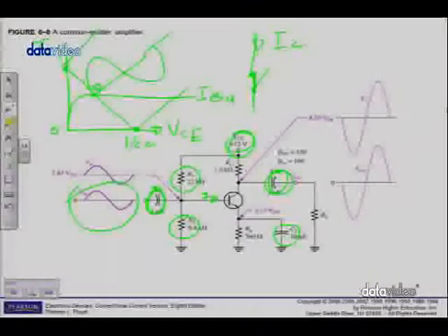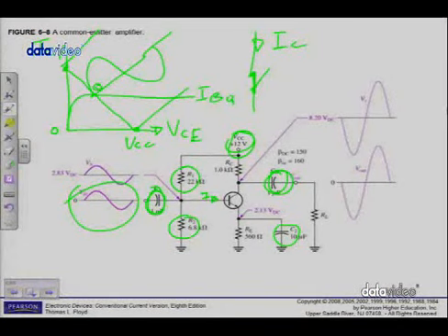This capacitor here and this capacitor here are called coupling capacitors. They couple my amplifier input signal and output signal. My input signal is not DC. In this case, I've got a sinusoidal signal, but even a voice is not a DC signal. It changes all the time, like an AC signal. I don't want my DC to influence my input signal, so I block the DC. Coupling capacitor. The same happens on the output. I don't want my DC to interfere with the output, where in this case I will connect RL. It will be a speaker, of course.